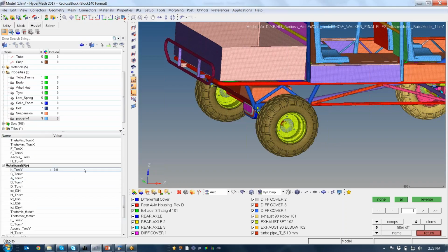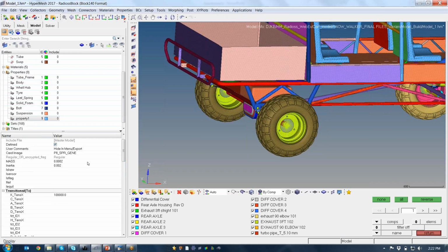But this may not always be the case. In a given model, you may have the revolute joint oblique to any of the global directions. Then you have to create a local coordinate system, and you can call it here. If it is aligned to global like this, it is quite simple.